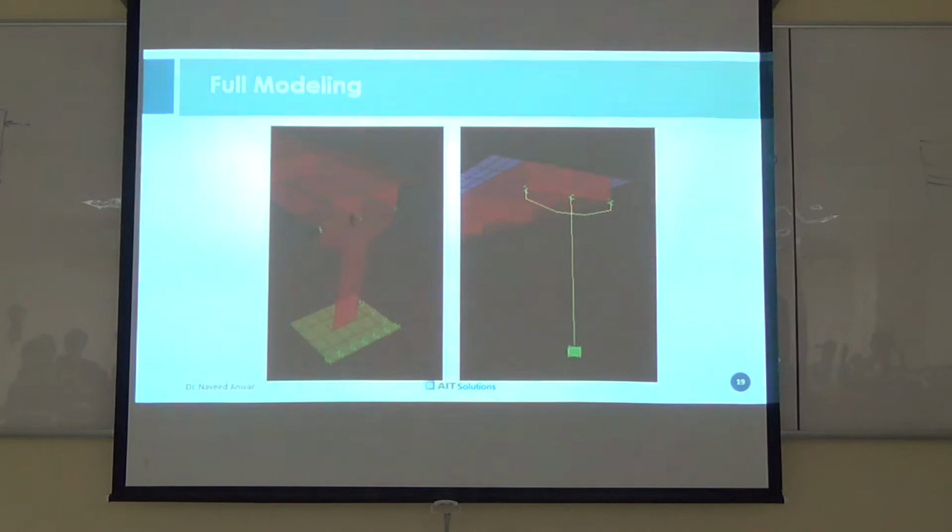And first, how to take this offset into account, that the depth, the slab is away from the bearings. That is something not new. People have known this for many years, at least 30 years, 40 years. But they didn't know how to solve this problem until we get this 3-dimensional modeling tools available. So I used all kind of rough things to try to accommodate, put a truss there rather than a beam, and do all kind of stuff to be able to do that.